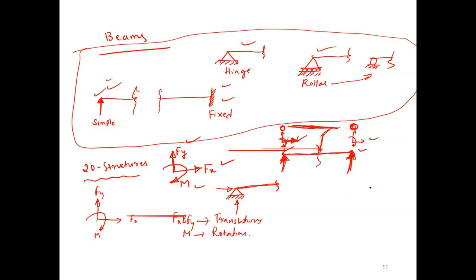So in any structure, the possible displacements are how many translations? Two translations and one rotation. Please keep in your mind, there are two translatory movements, they can move in axial directions x and y, and one rotatory type of movement. Now I am coming to hinge. So hinge is having two reactions. If you consider a joint, the possibilities are 3. Now because of this vertical reaction, this is 0. Because of this horizontal reaction, this is 0. But theta, that is rotation, or M is possible. Hence it will allow rotation. Hinge support will allow rotation,